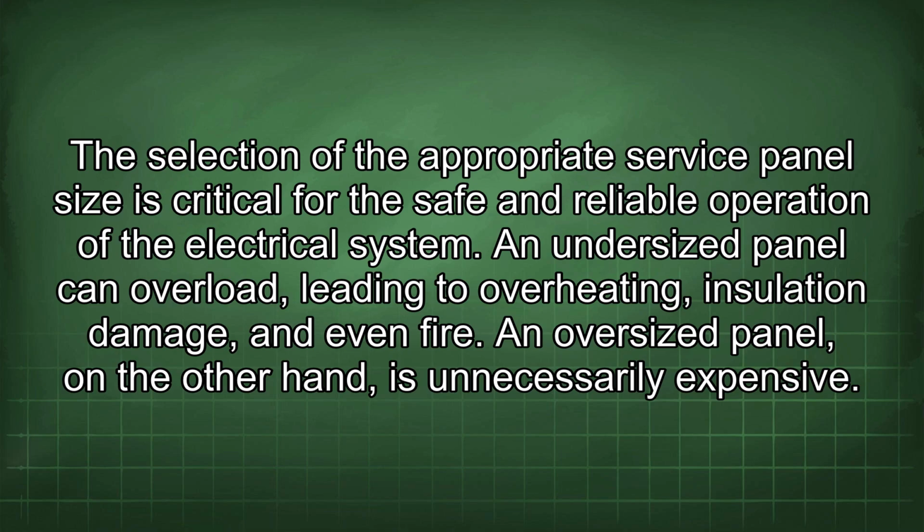The selection of the appropriate service panel size is critical for the safe and reliable operation of the electrical system. An undersized panel can overload, leading to overheating, insulation damage, and even fire. An oversized panel, on the other hand, is unnecessarily expensive.